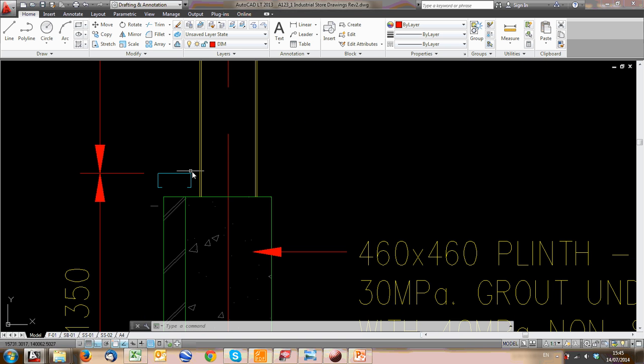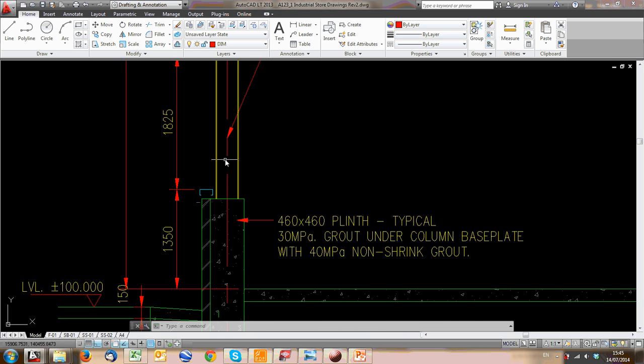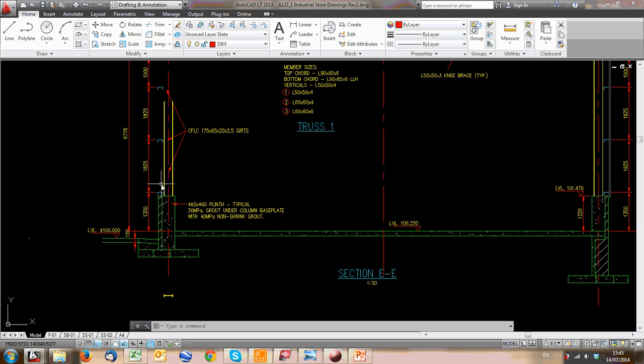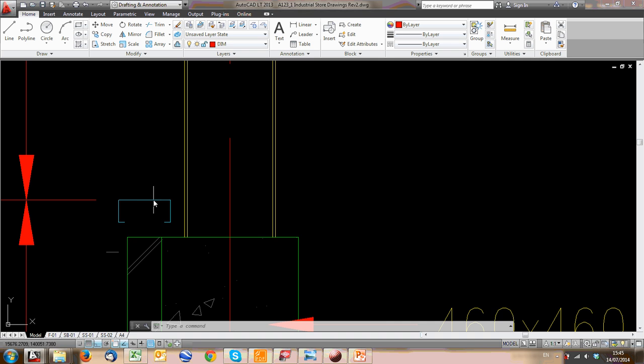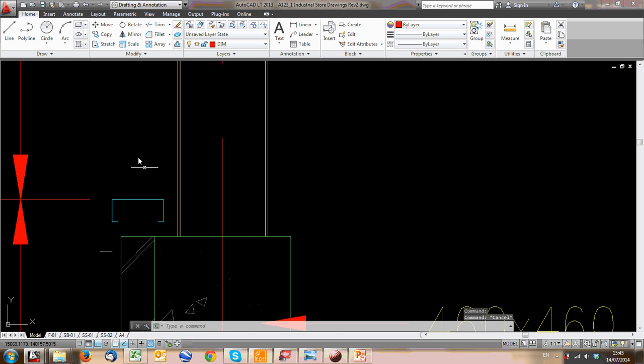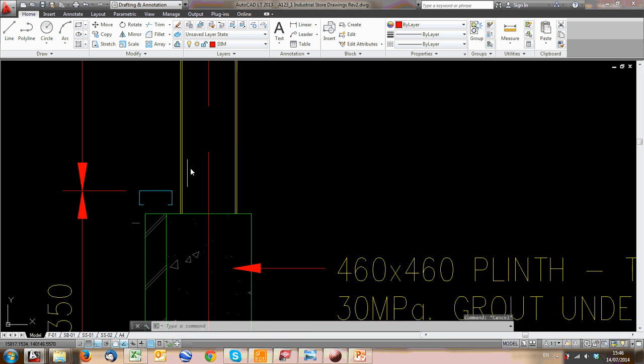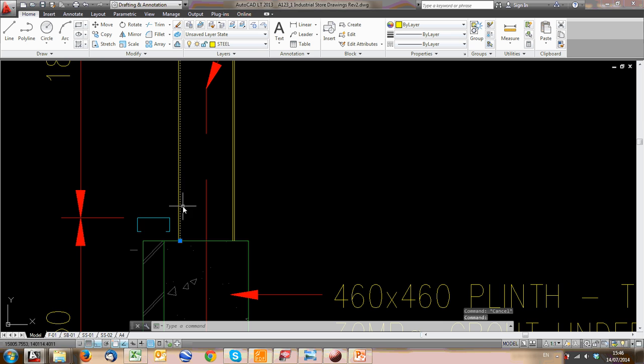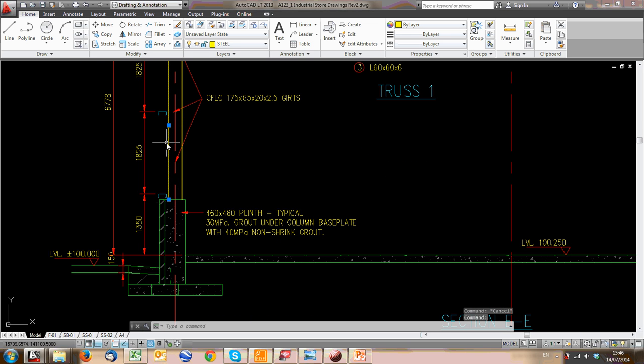And he is now out here, and one way to draw him is to use a polyline, because if you see I click on him, he comes up as one unit, as in all those lines are almost grouped together. And a useful tool for that is called the polyline. So I click on a polyline, and this then draws a continuous line all linked together, because you'll see these lines we drew, they're all on their own. They're not linked to anything else.